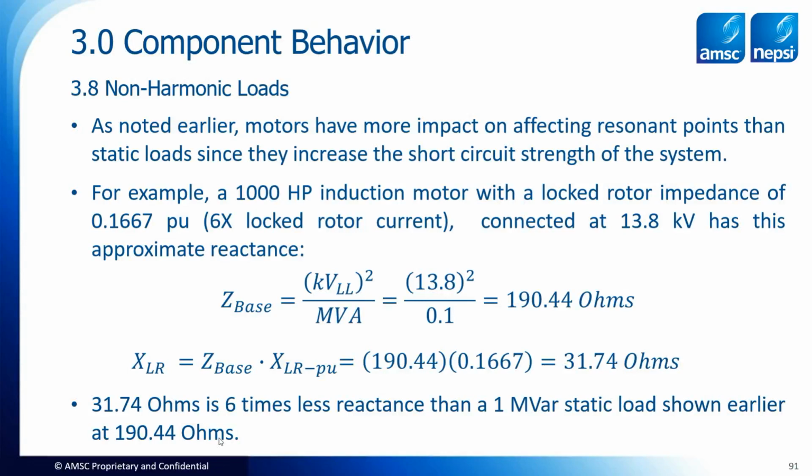So that is why I would recommend that when you're modeling systems and you're going down towards the lower voltage buses at 480 volt, if you're having to model those, you should definitely include at least all of the motors in a lumped motor form. In other words, if you know that you generically have 385 horsepower totalized of across-the-line motors connected, use a model with at least 385 horsepower and a typical amount of locked rotor, such as 6 times.